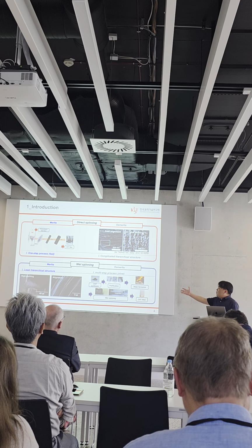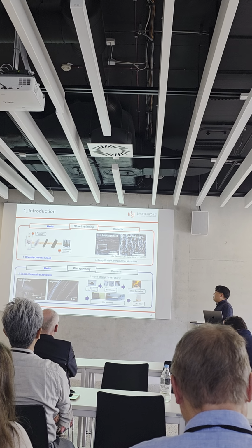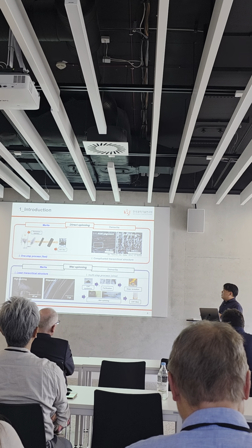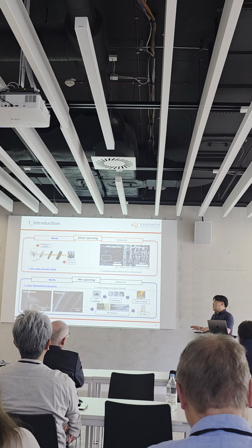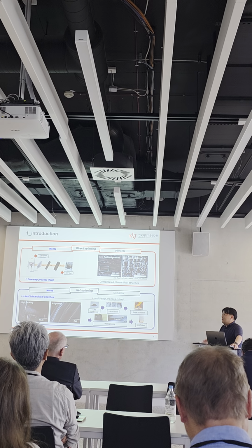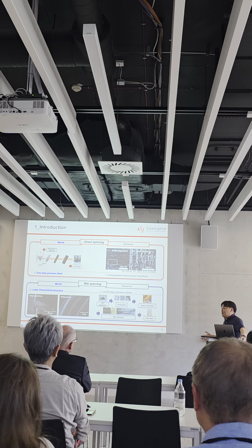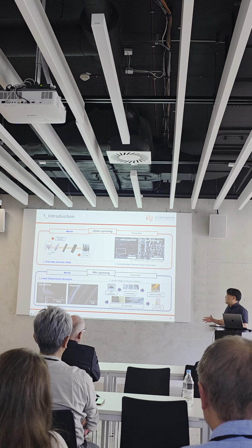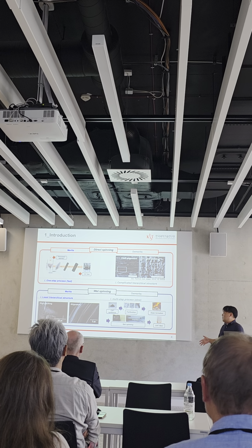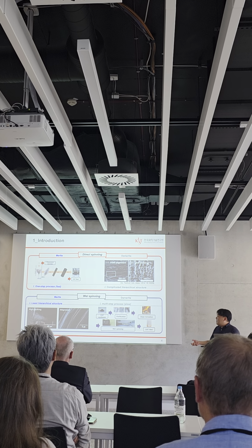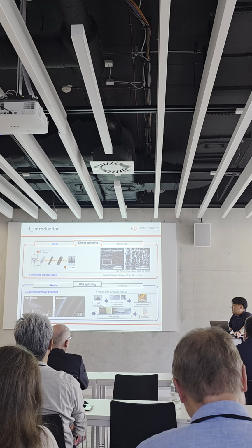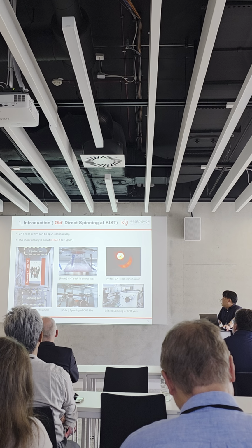The other one is wet spinning. Matteo Pasquale at Rice University developed this method, where the CNT powder is dispersed in chlorosulfonic acid. Chlorosulfonic acid is a very important solvent to disperse CNTs without any additives or dispersants. Then they form a liquid crystalline phase and spin the fiber with very well aligned and very dense structure. So it shows very good properties.